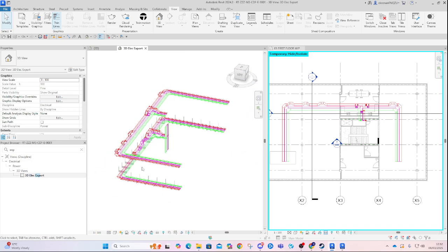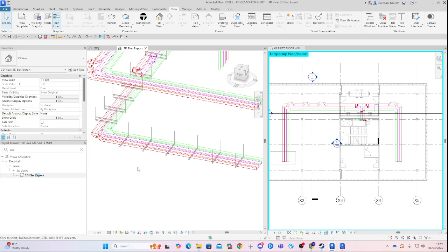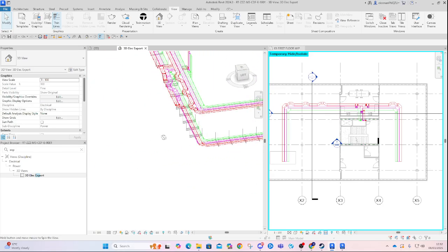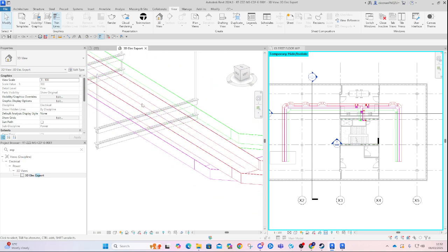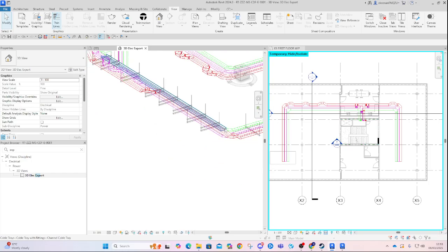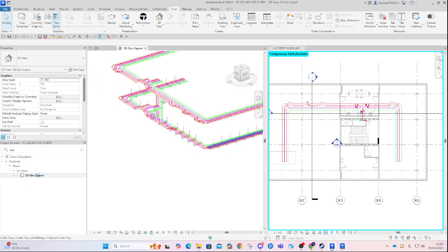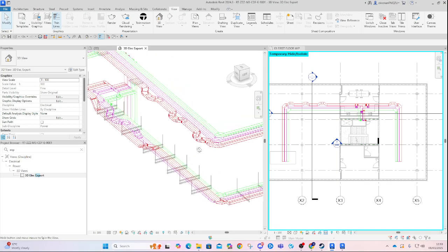on the first floor. The ground floor is done with two kinds of brackets. Around the back here, you'll see why I have a tiered bracket: we have a fire alarm cable tray at a higher elevation than the other two, for just this run here at the back, which is this run here on the ground floor. However, on the first floor, I don't do that.